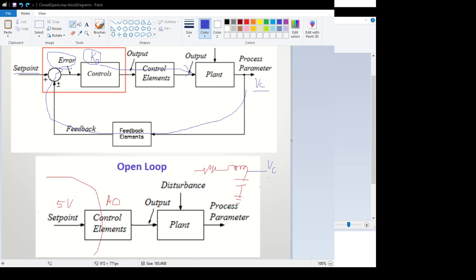So by using this, I can quickly switch my gain by flipping the selector switch. Okay. Additionally, I'm going to move out a 0 if the selector switch is in the center. So right now the selector switch is to the right, and so this is not active. But if I put it in the center now, what I'm doing is I'm outputting my control as a 0. So that basically means I'm just outputting 0 volts, which will discharge the capacitor of the RLC circuit.